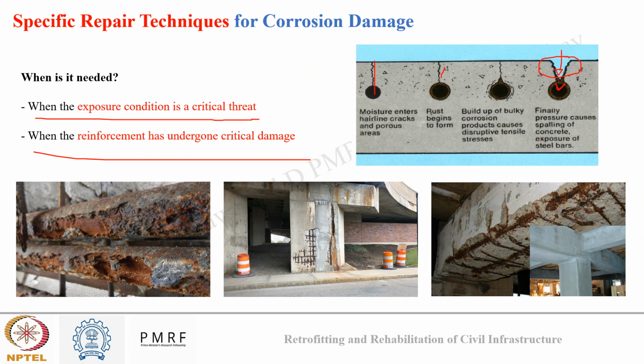When this state has been reached, just covering the crack may not be suitable because my exposure is very severe. It will crack the concrete again soon and demand repair again. Or suppose my reinforcement has undergone uniform damage, and it needs a control method which can make sure that this damage won't propagate further. For that case also we need a suitable repair technique for corrosion damage.